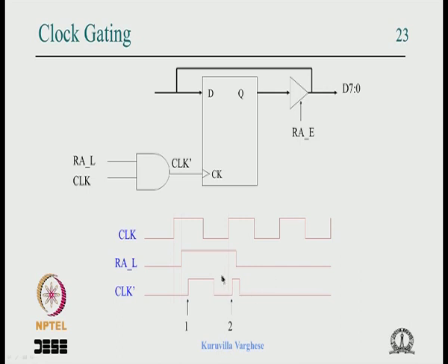So here, see the game, the trouble comes because our clocking should happen at this edge. When a latch signal comes here, the right time to clock is the second edge, because the data has changed at this clock edge and it has to propagate and come here.